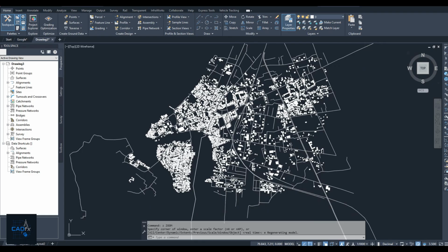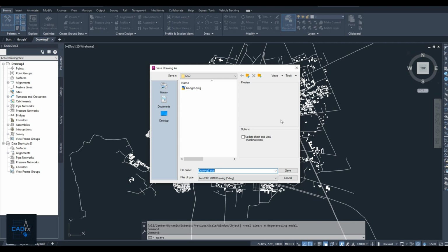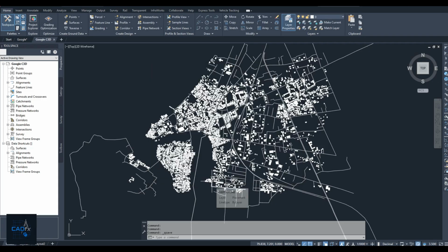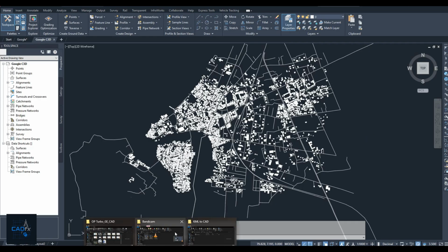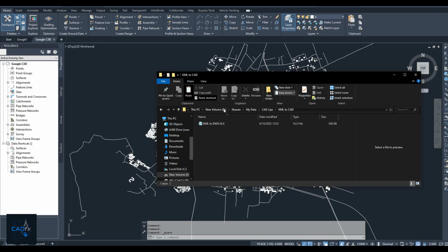This video demonstrated a complete, cost-free workflow for getting detailed map data into your professional design software. First, you learned how to use a free online tool called Overpass Turbo. We created custom queries to select specific data like roads, rivers, and buildings, and we used the OpenStreetMap wiki as a reference to ensure our queries were correct.